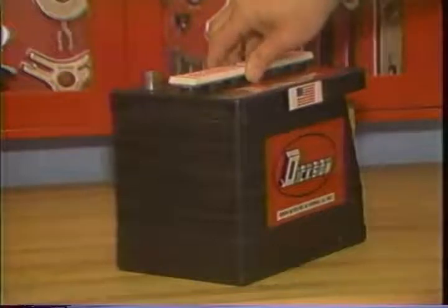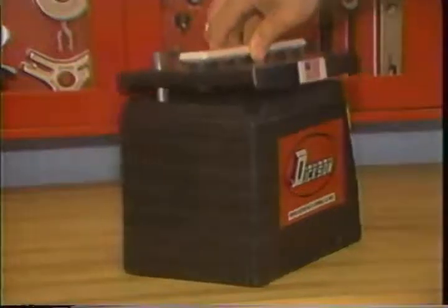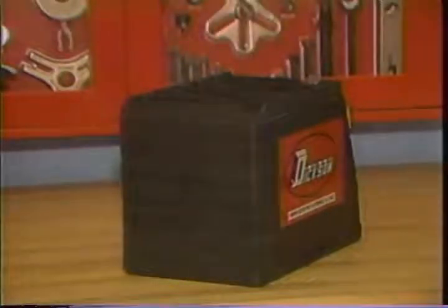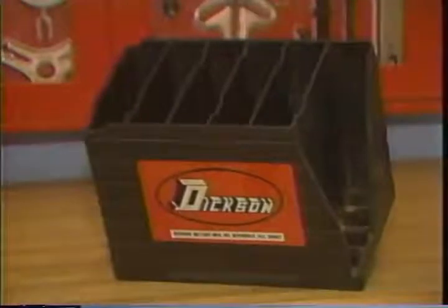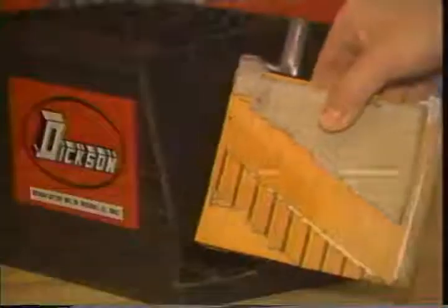Here we'll show you how a battery is constructed. By removing the cover, you can see the compartments in the battery case or housing that form the cells. Battery housings are made out of a synthetic plastic material designed to resist acid corrosion, temperature change, vibration, and other forces. Each compartment in the housing holds one of the battery cells. The positive plates, negative plates, and separators slide down into the cell compartments of the case.